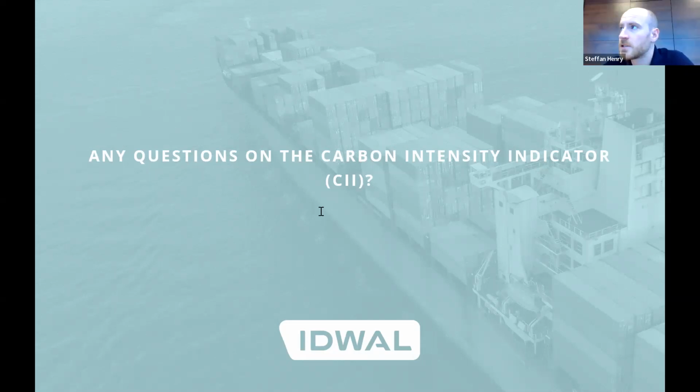Well, it's not necessarily that you have to slow steam to comply with CII. It seems quite basic, but you have to reduce the amount of fuel you use. There are other options apart from slowing down. Like Ben said, there might be some weather routing things you can do, and maybe improving the power management. You might want to change fuels. So in those cases, you'd be able to maintain your speed, but also comply with your CII.